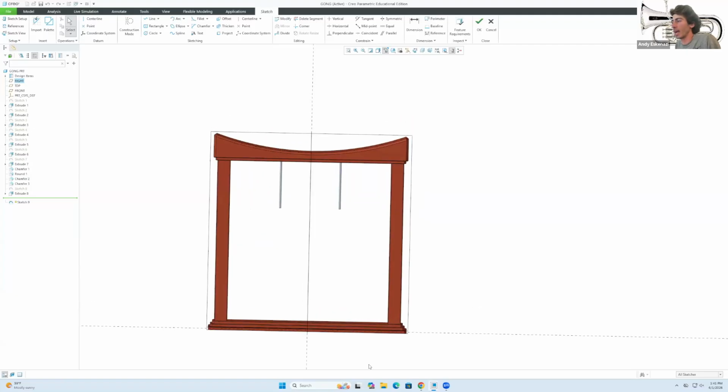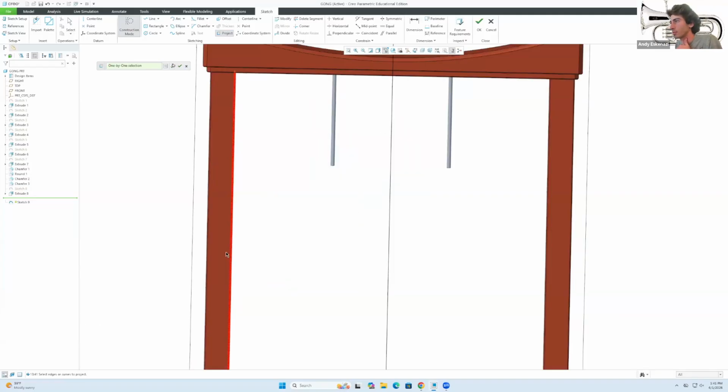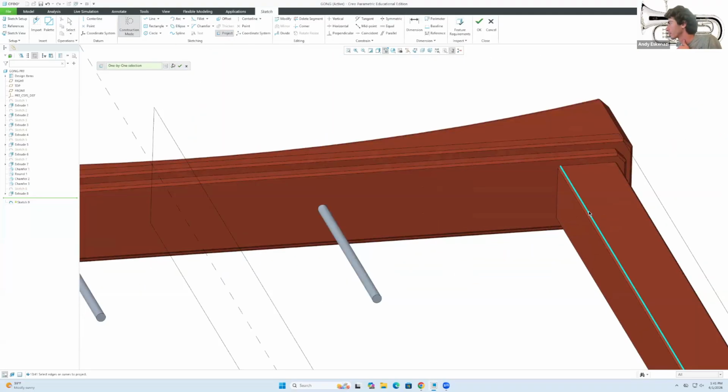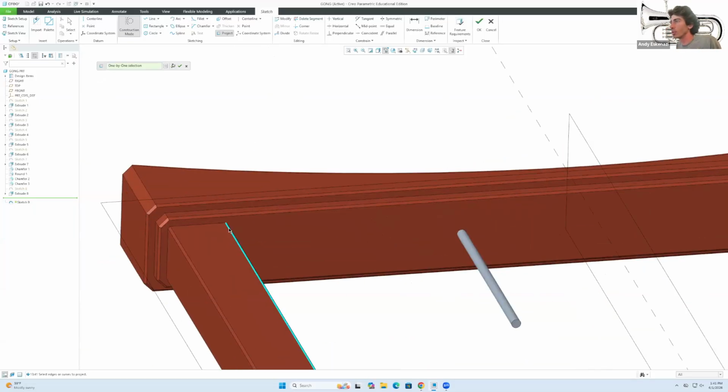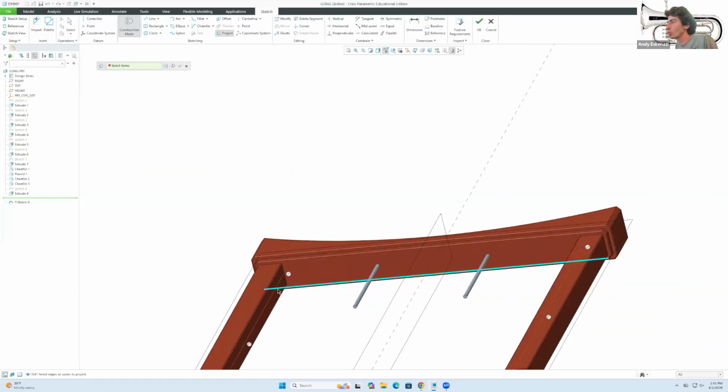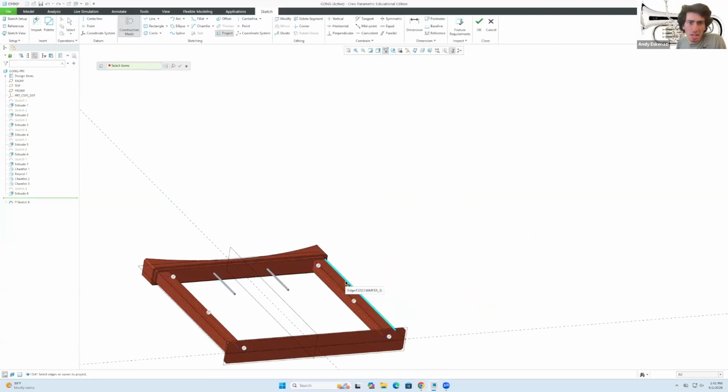And looking at our command from last time, if I want the circle to be, say, halfway between these 2 points, what I can do is go to our frame construction mode and then project. And I'm gonna project, what line did I project? I'm gonna project that line, and I'm gonna project this line. So essentially what it created is two construction lines that represent edges.